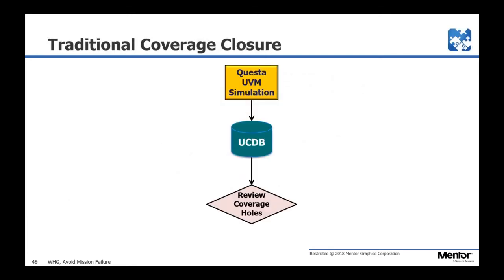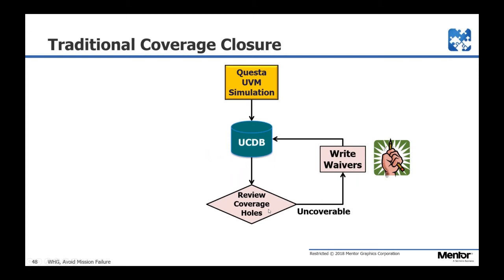So what often happens is we run our test suite, we collect all the coverage information, we look at that, and then we have to manually make decisions and say, you know what, I think those lines are uncoverable because this is a reusable block of code, and the way that I've configured it through my generics or parameters or whatever, those lines of code are unreachable.